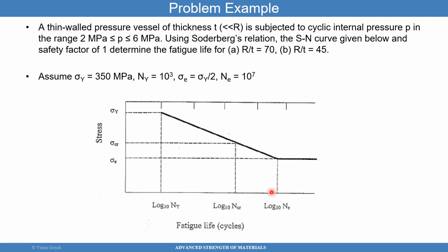We'll get started then. And this stress strain curve most likely is true for full reversal. What that means is that if I choose a value here, say 20, that 20 megapascals is going to be the alternating stress.